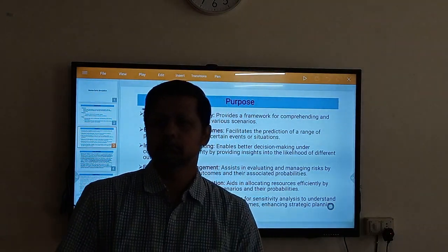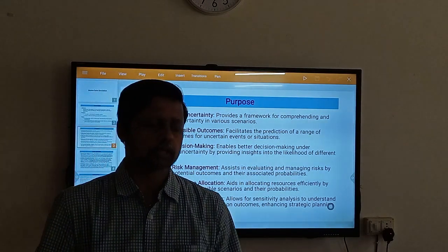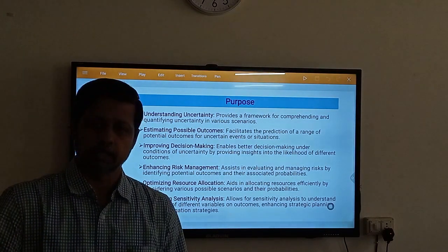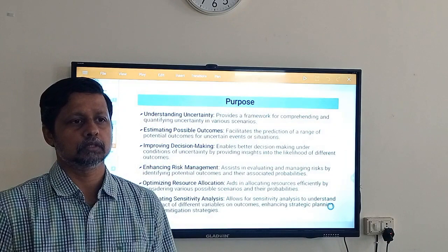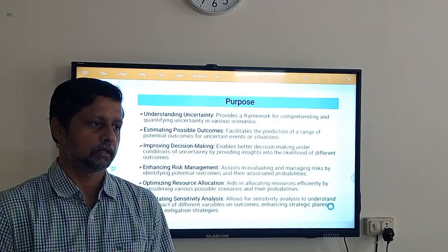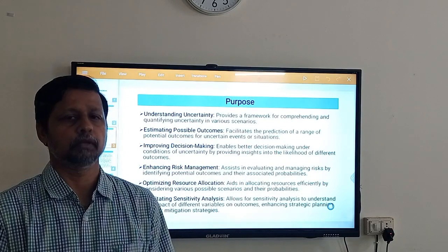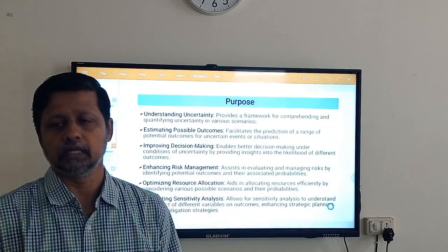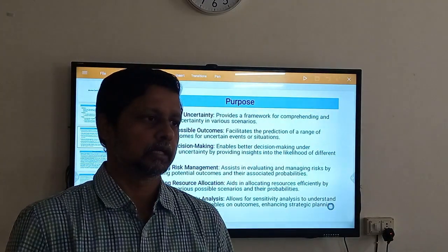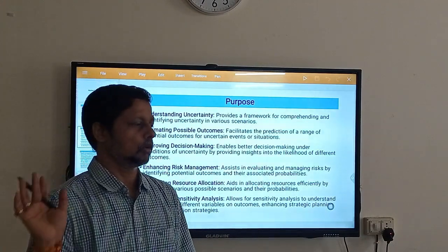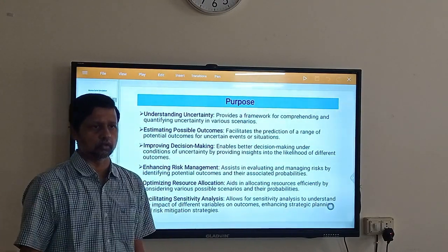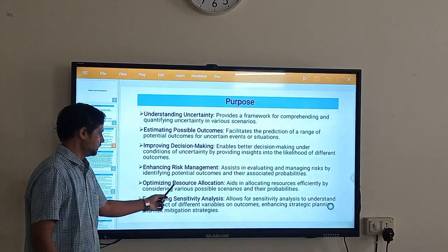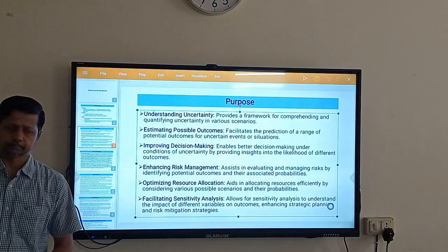Even if it is 2 hours, there is no guarantee that where your plant is commissioned, your nearby OEM will be able to provide those resources at your doorstep within 2 hours, or within 1 hour, or maybe within 6 hours, or within a day. So in those cases, you have to keep the redundancy of those critical components in standby mode in your warehouse, or in your store where you can provide the necessary services. So that way you will be able to optimize the resource allocation.